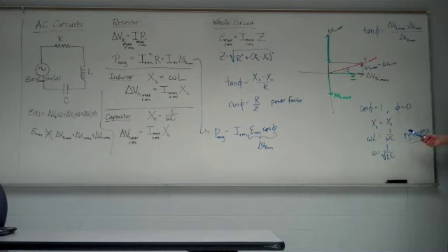If phi is not 0, if XL does not equal XC, then we have some other power being dissipated by the circuit. It's just not the maximum possible. So this is a special case. Not all circuits will experience this. So please don't try to use omega being 1 over the square root of LC for all of your problems, because it will not necessarily be.